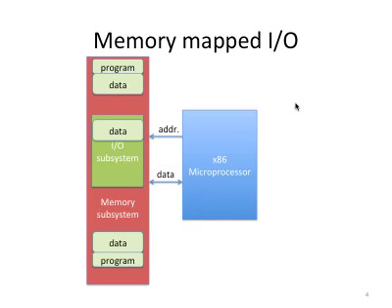So the way to access these I/O devices, or part of the I/O subsystem, is to use some special addresses. Overall, by looking at the address, you don't really know whether it is a real memory chip or is mapped to an I/O device.